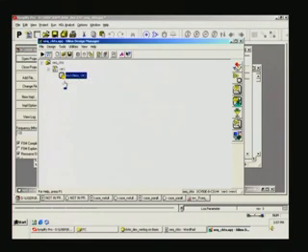So, as I mentioned, in order to avoid overwriting, these tools normally they do create different versions, revisions, and that is how you have here. And now what the next step here is, the place and route already knows that the input file is sequential circuits .edf, and this will be taken as the input file and processed further.